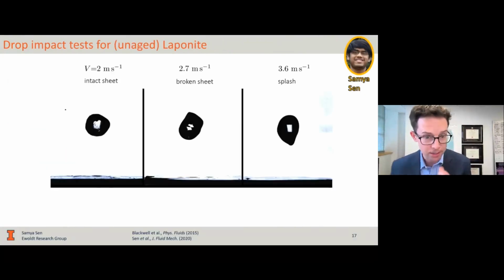So the droplet size is tricky because if you've ever tried to drip a viscoplastic fluid out of your toothpaste tube, for example, you know that it doesn't form a sphere at every length scale because the yield stress resists the effects of surface tension that are trying to form a minimal surface. There's a nice dimensionless group that compares those two things. All of our droplets here are large enough that surface tension doesn't have the strength to form this into spheres.